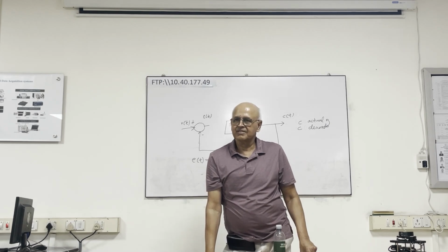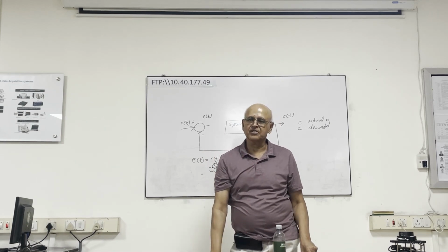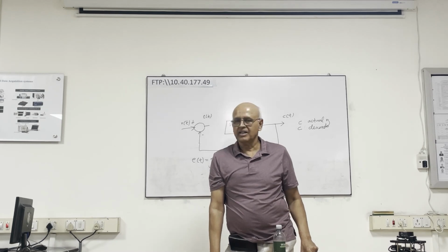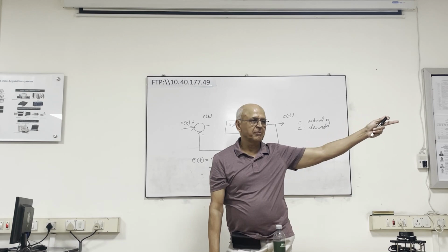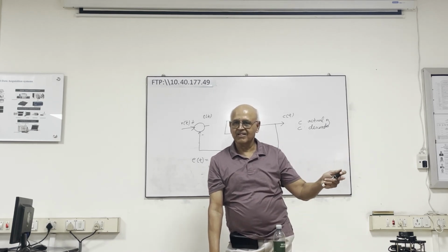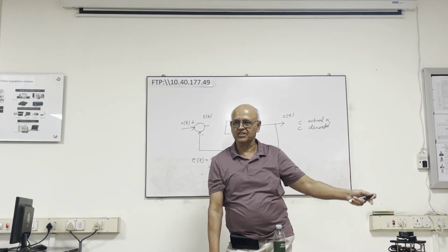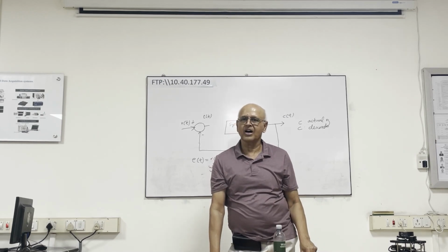Now that's not a closed loop control system, because what is missing is you have to monitor the temperature in the room. Just turning it on for a certain amount of time, there's no guarantee that the temperature in the room is going to reach what you want it to, because it depends on the outside temperature. The heat is coming in through the walls at different rates depending upon the outside temperature, right? So unless you pay attention to the quantity to be controlled, how can you control it?